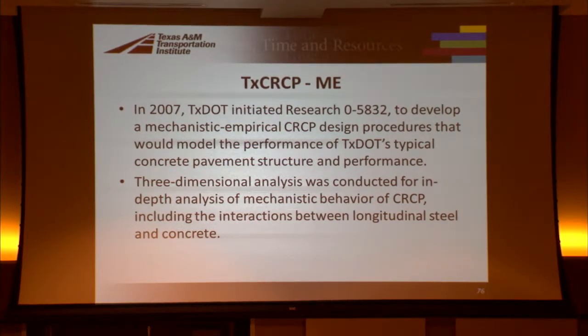CRCP is continuously reinforced concrete pavement. There are only joints at bridge ends and where it stops at end of day's paving. We expect it to crack at a certain crack spacing, usually 3 to 10 feet, and those cracks are kept closed by steel. And we developed, there was a project that Texas Tech had led, but TTI participated in. I was on the project. Dr.